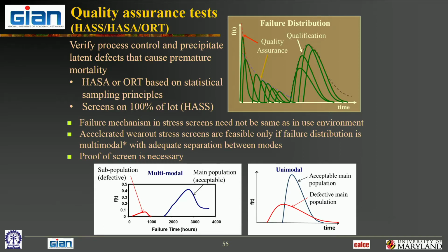Stress screens, people have become very, very nervous about it. Even non-stress screens mean you're going to handle all these parts, and handling damage alone can sometimes ruin the reliability downstream. So all of those are big problems with screening.